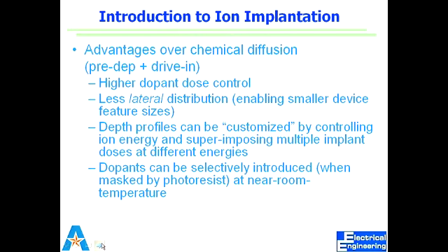So that may be 10 raised to power 16 here, 10 raised to power 17, 10 raised to power 18, done by successive implantations. Right? Part of the reason is if I want to do this much in one go, I will end up with much more lateral diffusion. Instead of that, it's done in what you call superimposed multiple implants at different energies.